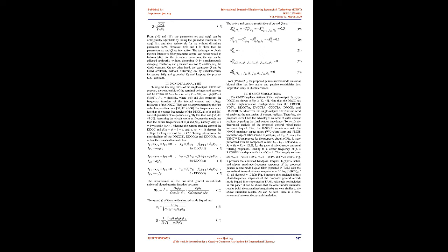Filters using only single-output DDCCs have the advantages: 1. No need of extra current replicas degrading the final output impedance, and 2. Simpler implementation configuration than multiple-output DDCCs. This represents an attractive feature from the chip area and power consumption point of view.